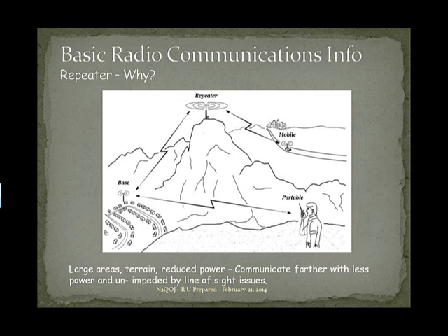The reason for that is the repeaters are typically mounted on mountains at an obviously elevated altitude. They typically are operating with very good equipment, antenna structures, antennas with gain for both receiving and transmitting. That kind of installation really mitigates several items. It mitigates terrain issues.